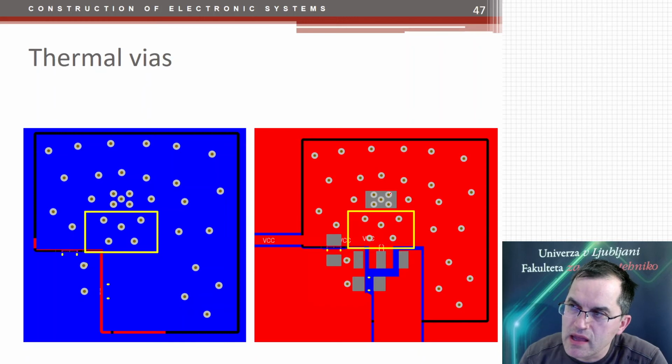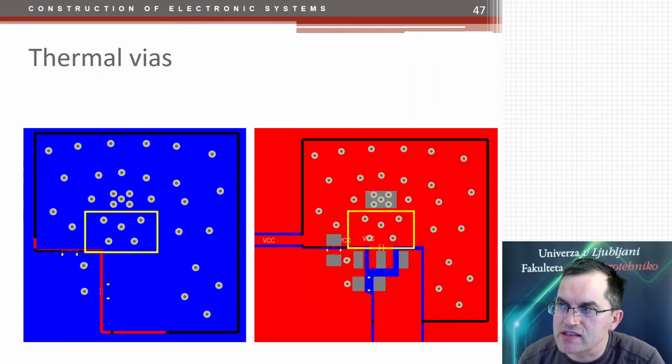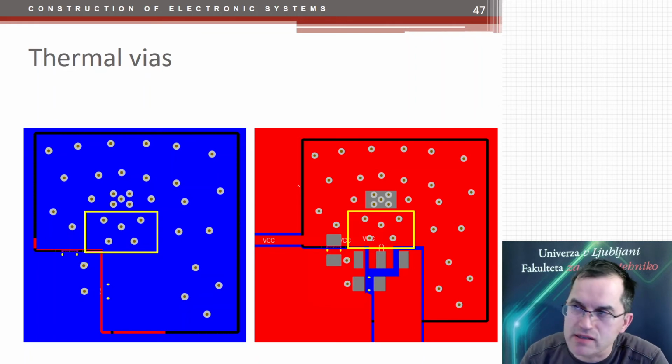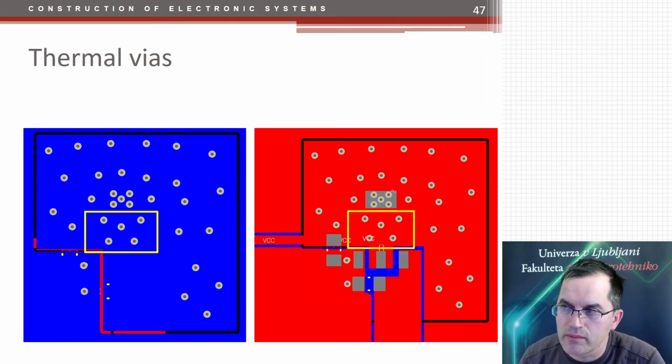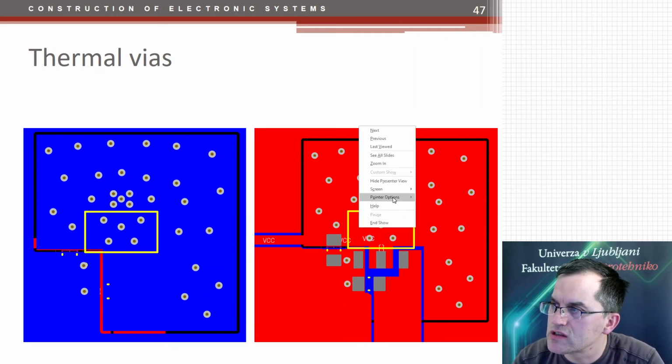should be placed the most dense, just under the pad which has the highest heat, which is the highest heat source, like this thermal pad, cooling pad on that component here. So here you put the most wires, but you don't put them around as close because you want that heat also to be transferred laterally. And I have a red pen and it can be seen here. So maybe I can just switch it.